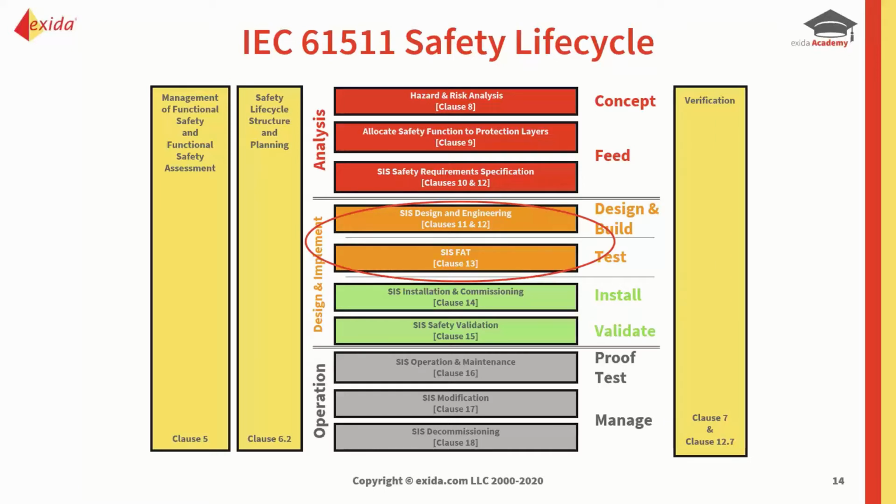Oftentimes there's a lot of emphasis on hardware in courses, but we still have to consider the application, because even though we've got a potentially high integrity logic solver, such as a SIL3 logic solver, it still needs to be programmed. And if we do it wrong, then we can end up with, again, systematic issues creeping in. So this is why it's so important to have a structured methodology when it comes to doing not just the hardware, but also the application software.